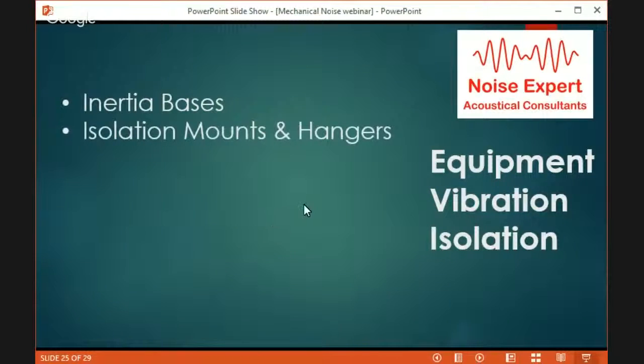We generally recommend you just use one isolation system. You don't try to double them up because the relationship one to another could cause some problems. You're getting natural frequencies from each, and if they line up, it could be not as helpful as just having one isolation unit.